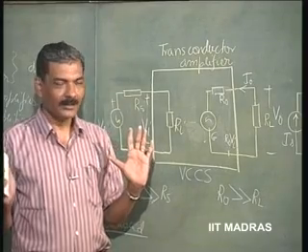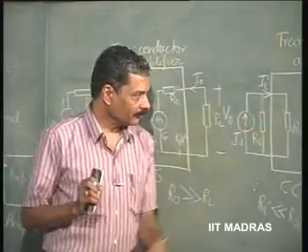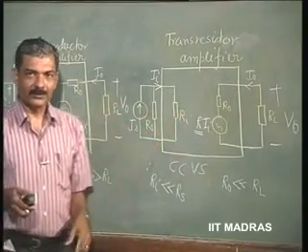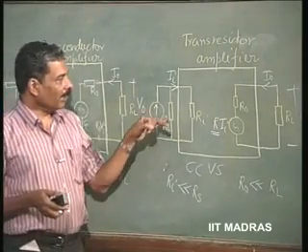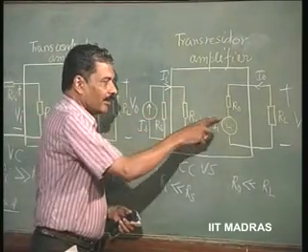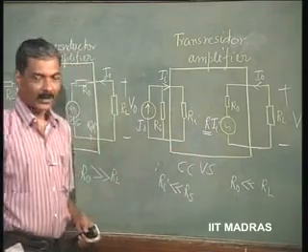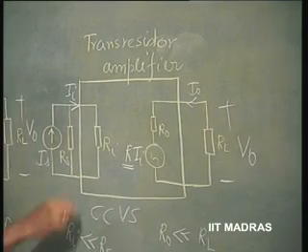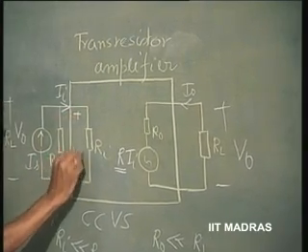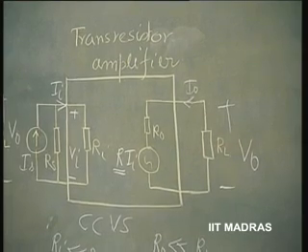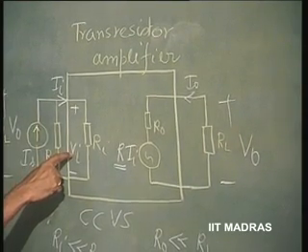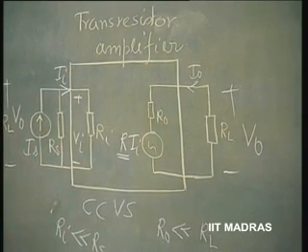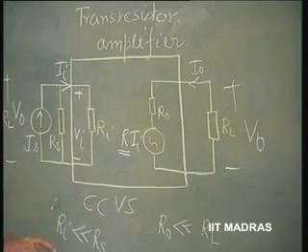Is this clear? Next, let us see that. This is already a voltage source. Now, the voltage here is R times Vi. I would like to represent this in terms of Vi. Let us say this is really the Vi of this stage. So, I know that Vi is nothing but Ii into Ri. Right. So, Ii is nothing but Vi by Ri.